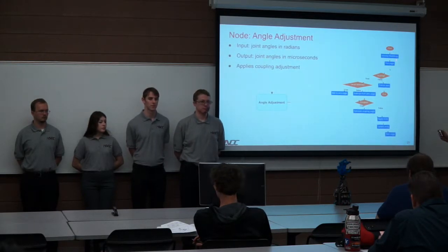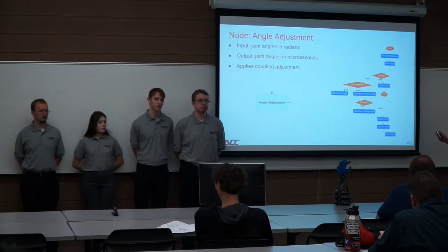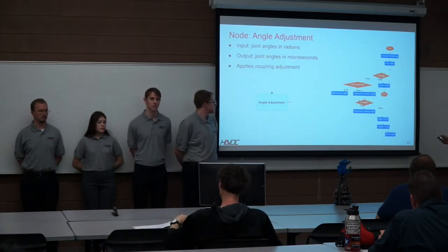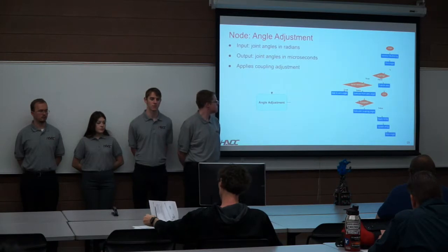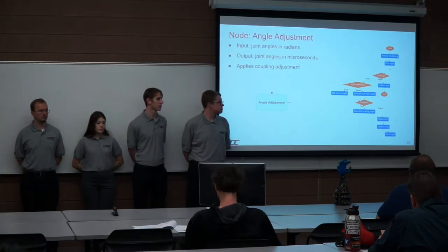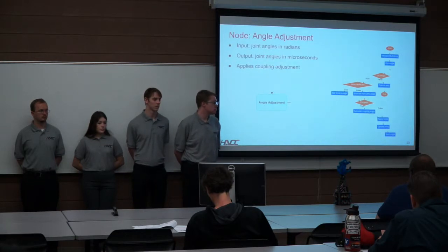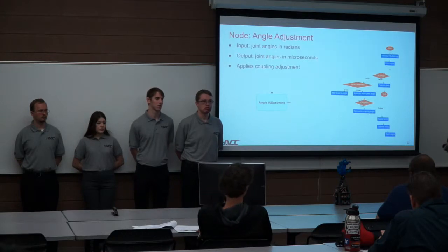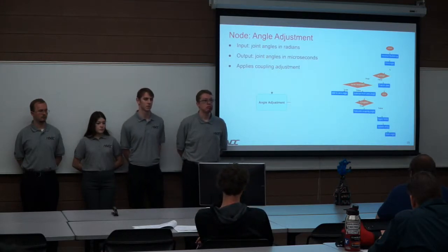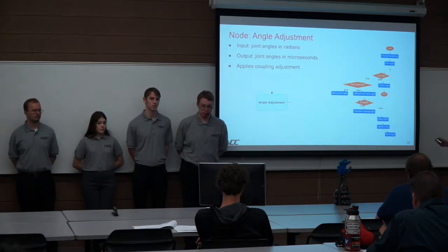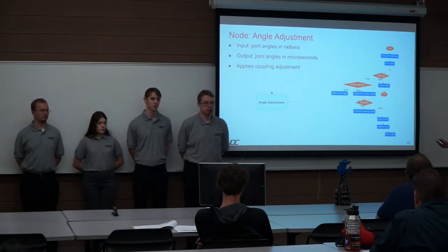So first, again, we initialize a multi-array and cycle through the angles in that array. We check if our servo is reversed, because on some fingers, curling is a decrease in the servo angle, and on other fingers it is an increase. So we want to make sure we apply the right calculation for that. If the servo is reversed, we'll add to the zero angle. If it's false, then we'll subtract from the zero angle.